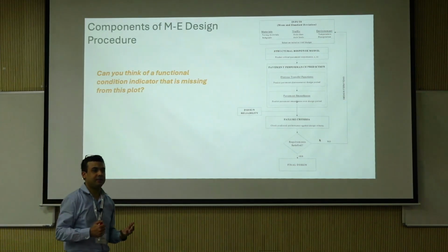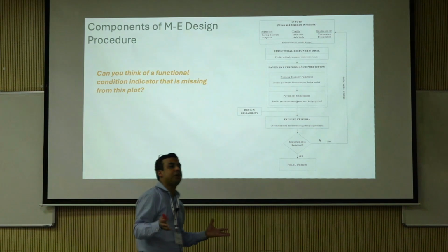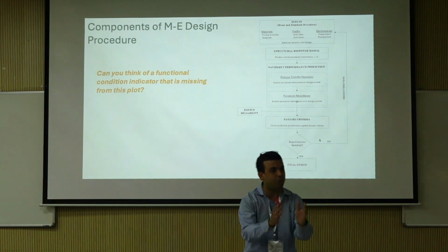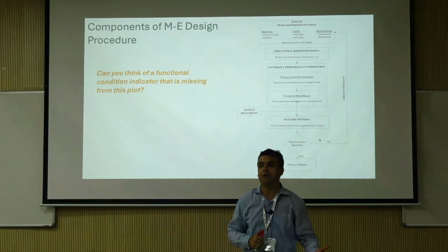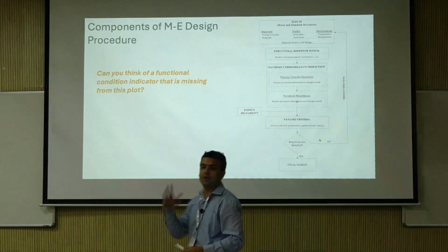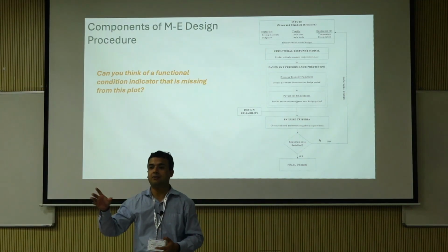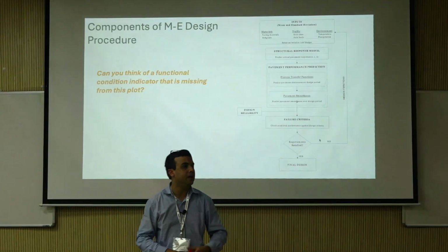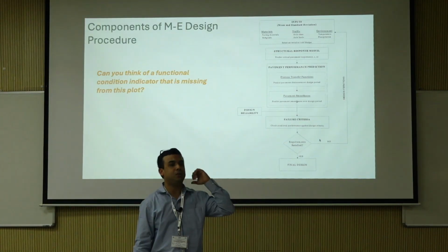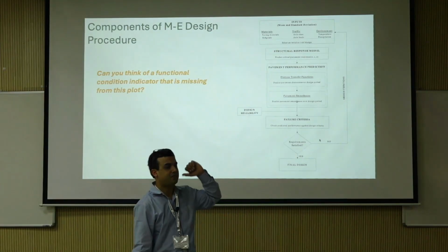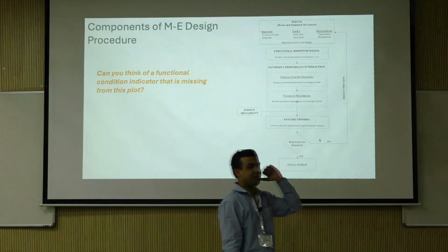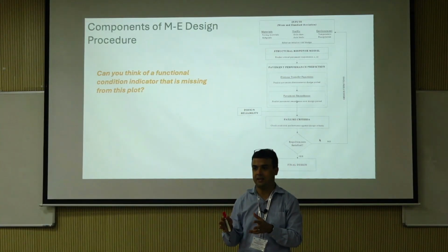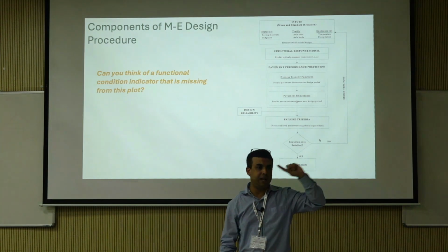Level 1 is you are in a purely research environment where you have tested everything for what you are trying to do. Let's just say tomorrow IIT Bhubaneswar is going to construct a pavement test track. So now you are trying to characterize the material to construct it. You bring the soil, you do all the classifications, you do all the shear strength testing, the resilient modulus testing, and all the inputs go directly into your mechanistic analysis procedure. That's called level 1.